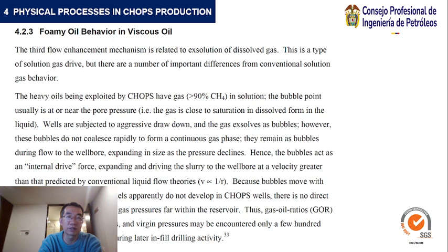Foaming oil behavior in viscous oil. The third flow enhancement mechanism is related to exhaustion of dissolved gas. This is a type of solution gas drive, but there are a number of important differences from conventional solution gas behavior.